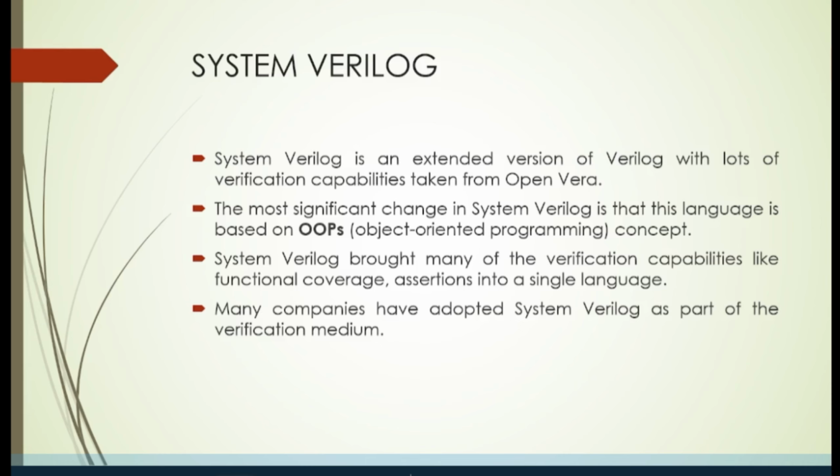Why? Because as I told you in the starting itself, SystemVerilog has many extended features which were only introduced in SystemVerilog, because Verilog doesn't contain features like OOPs, assertions, coverage, constraint randomization. In Verilog, you don't find any of these features, which is why, by using all these features, we are making SystemVerilog the most adaptable option for verification, right?